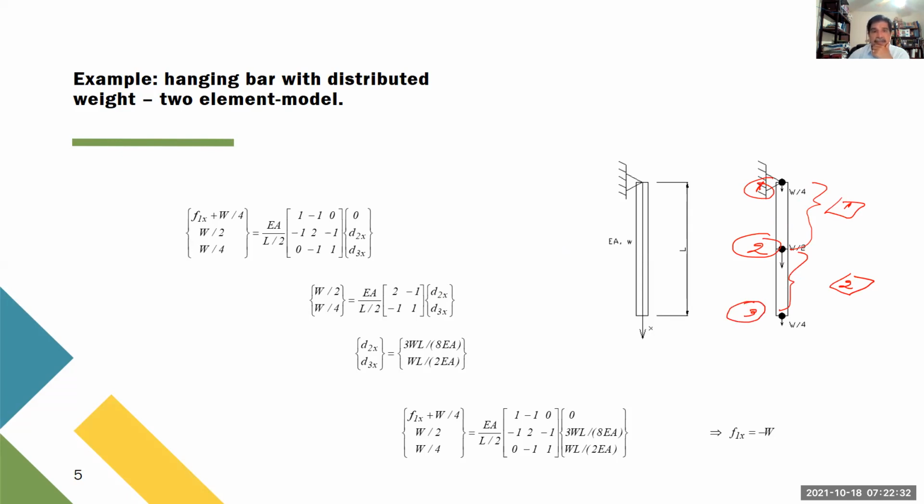So in this case, this is the system of equations, okay? This is something that we have done in class. So we see that this part here belongs to element 1, and this part here belongs to element 2. That's why we have a 2 here, because at that point we added the contribution from each one of the joints.